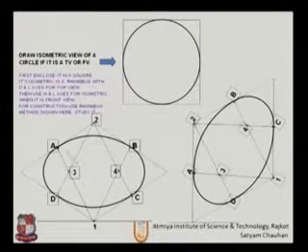And hence the first step is to identify the midpoints and give the names A, B, C and D. Simply join the smallest distance points, the smaller diagonal points, give them the names 1 and 2, and join the midpoints from 1 to A, 1 to B, similarly 2 to D and 2 to C to get point number 3 and point number 4. The same steps will be repeated here.